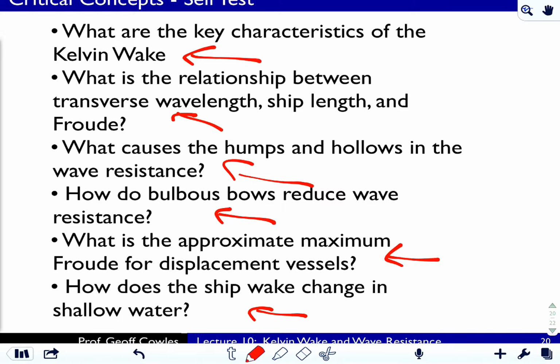Their wave faces are at an angle to your travel, and you can measure that angle, and essentially you have a cone of influence, just like you have for supersonic flight, completely analogous, except that you're not dealing with sound speeds, or the speed of sound being fixed by the medium. You're dealing with the speed of the ocean wave being fixed by the medium, and your characteristic non-dimensional number is not the Mach number, it's the Fr_h, which is the depth-based Froude number.